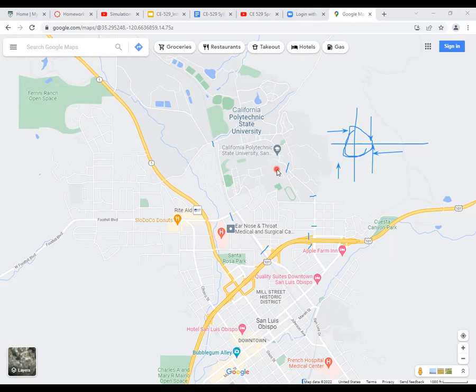So your roadway geometry, number of lanes, bike lanes if they are there, vehicular count, bicycle count, pedestrian counts at different locations. And then you said signal timing. Yes, absolutely, signal timing. You need that. Well, what else? So I think those are all important things.